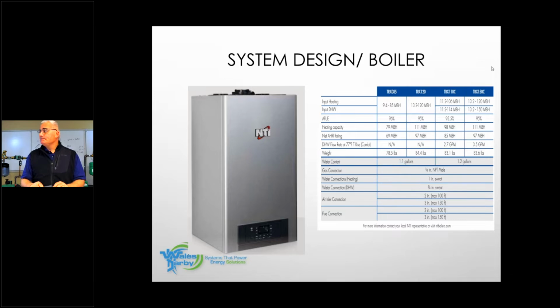Yes, sir. We got a question. As soon as you wrap up your boiler talk, there was a question about the windows on your heat loss design, and does the direction of the windows matter? No, that's a great question. Johnny Barber put this to me very clearly, because I kind of asked that question once myself. We do the heat loss based on the average coldest day of the year, and it's definitely going to be coldest that day at night, and it's dark all the way around the house. So it really doesn't matter.